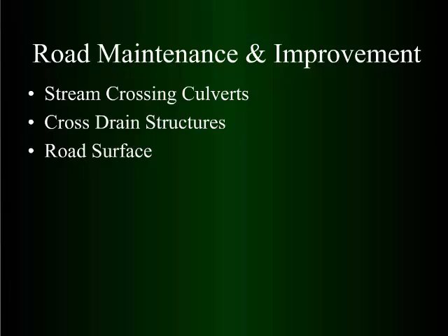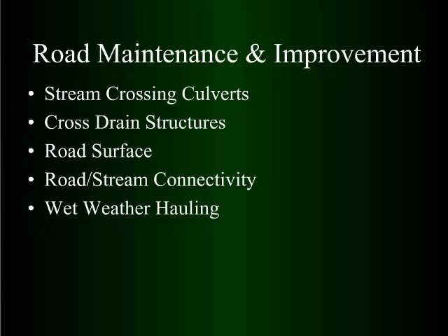It's always nice if you can keep traffic off the road during the wet season, because the tire tracks generally become streams. The other thing is looking at the road stream connectivity, basically dumping your ditches into live streams and the problems that causes. The other thing would be wet weather hauling. In this intermountain area, the spring breakup would be equivalent to the wet weather hauling.